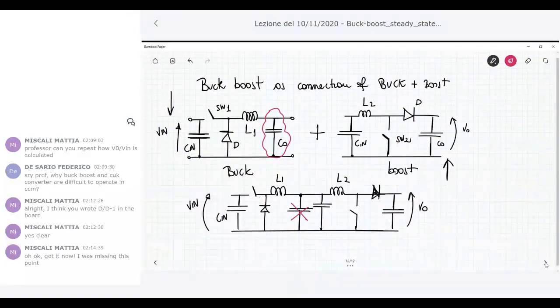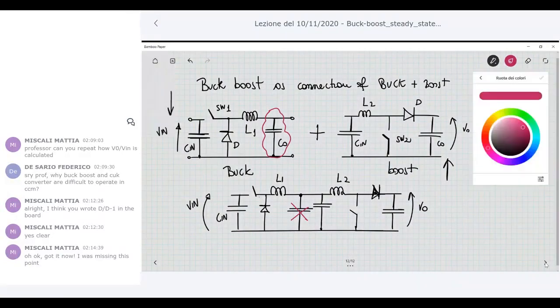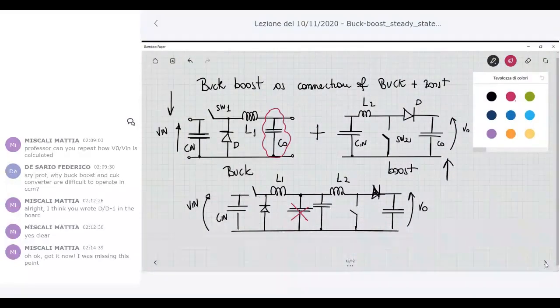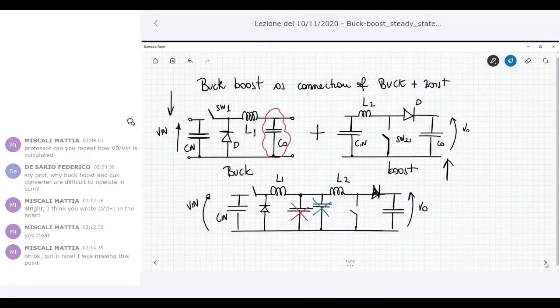And then always you have to insert a low-pass filter at the beginning, at the input side, because you have to contain the electromagnetic emission inside the converter, not to expand all over surrounding equipment, etc. So basically, you can say that even the C in capacitance can be eliminated, okay? The operation of the converter is always the same. So there is no modification of standard operating mode of the converter if I eliminate C0 for the buck and C in for any converter.